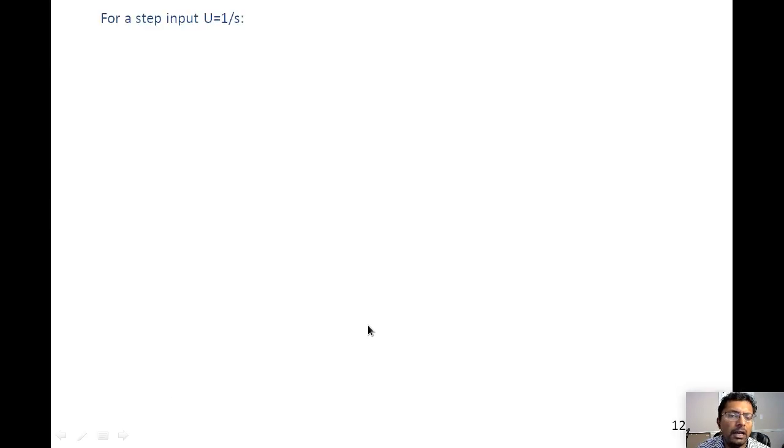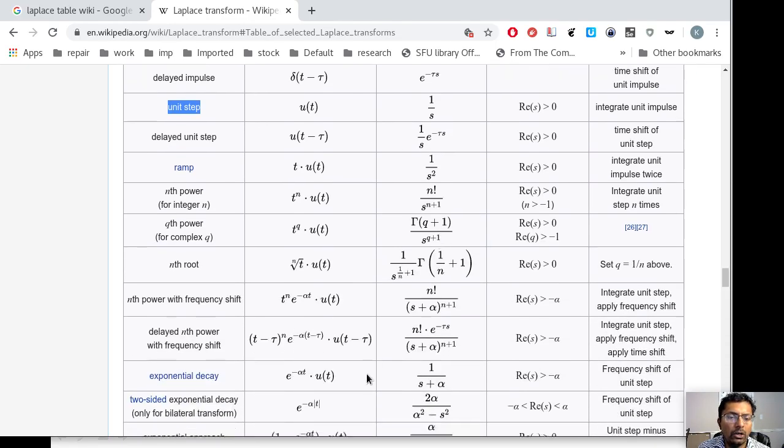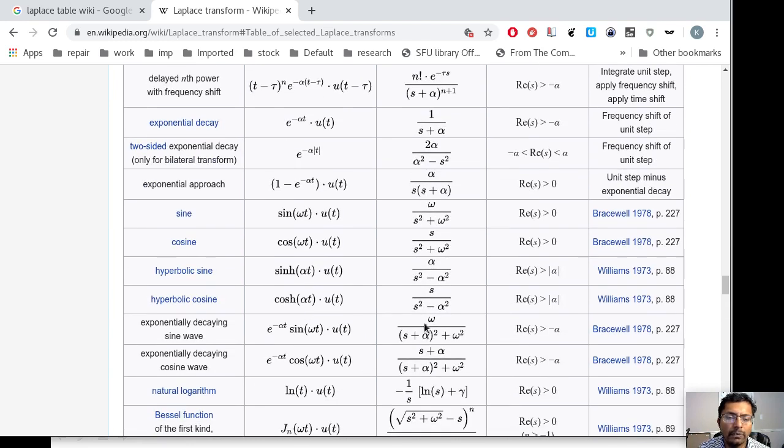So once you have that, we're going to calculate the response of the system. It basically becomes just g times 1 over s. If we go back, we have two options over here, right? We can multiply the denominator out, where I'll get cubic terms, and then try to figure out what the inverse Laplace is going to be. But if you go to the Laplace table, it only has terms up to s squared. So this would be a problem. So what we need to do is go the other way, and figure out some way of transforming this equation into a combination of lower powers of s in the denominator.